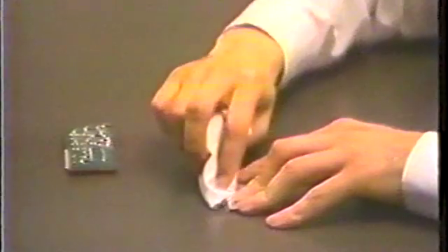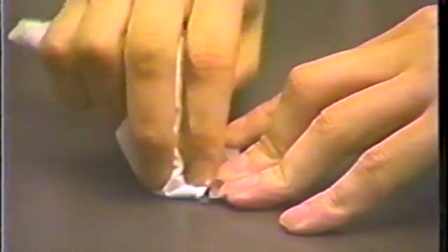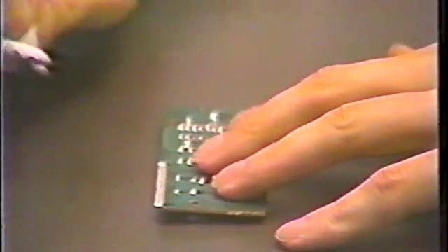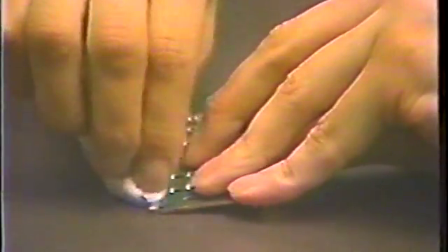If the LCD is to be reused, clean it as well. LCD electrodes are difficult to see, but can be seen by tilting them so they reflect light. Align the electrodes with the black stripes on the heat seal.